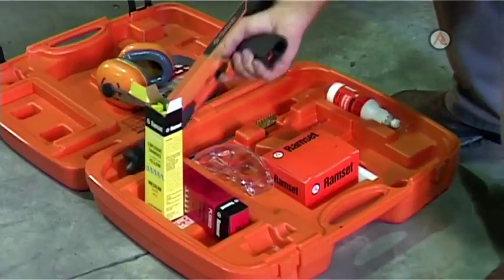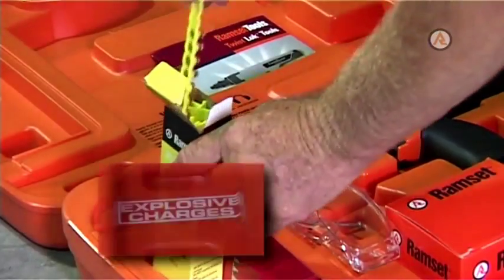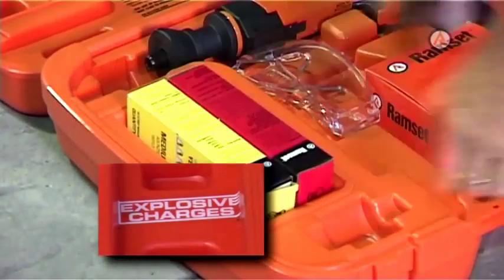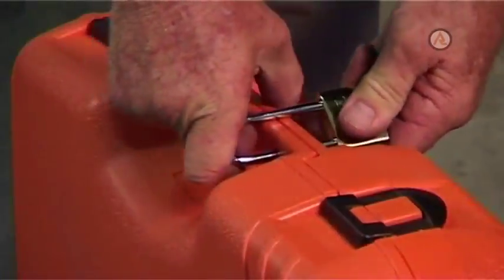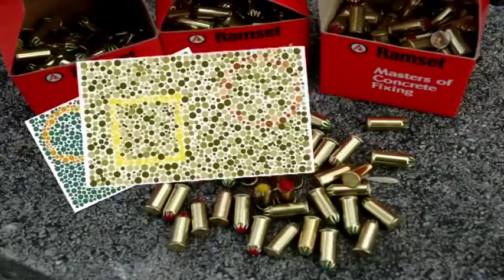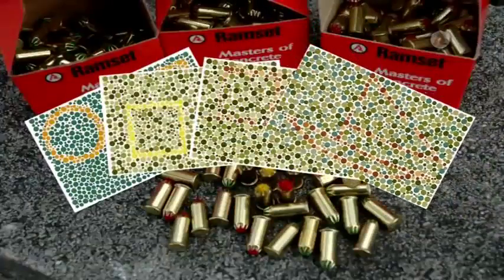When not in use, the power loads, which are commonly known as charges, must be stored safely in a lockable, damp-proof container that clearly indicates the words explosive charges. It is essential that operators who use these types of tools are not colorblind to ensure they can differentiate between the different strengths.